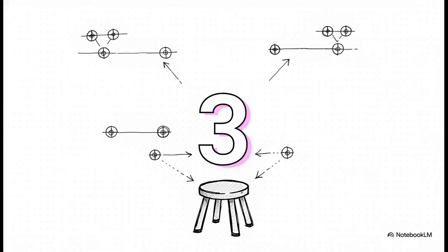The answer is 3. Yep, paragraph 7.24.4 dictates that a primary datum plane is established by at least 3 target points that are not on a straight line. It's just like a 3-legged stool. It literally never wobbles, even on a terribly uneven floor. Building on that, a secondary datum plane usually requires 2 targets, and a tertiary requires 1. This 3-2-1 principle is the absolute rock-solid foundation of fixturing.